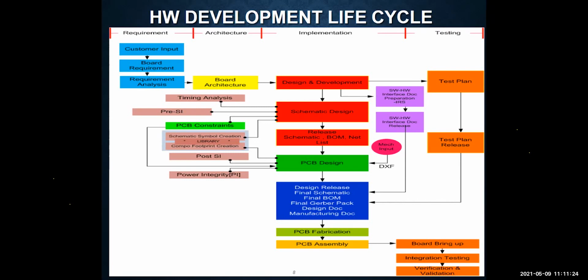Schematic design will include components, like when you have a resistor or a capacitor, you need to create some schematic symbols. And for ICs, some processors, all these things happen in the schematic design. So once your circuit is ready, you need to check. Definitely it's a good design practice and it's a must. You need to check whether your connections are proper or not, and whether you have made any wrong connections. All these things will be checked during design rule check, DRC.